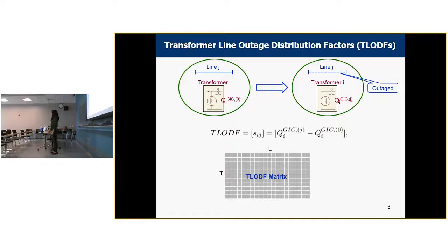So now the purpose of the algorithm that we developed is to minimize the total losses in the system. So for a network, we want to use line switching to minimize the losses. And the question is, what are the best lines to select for opening so the losses are minimized? We use a sensitivity analysis to find the best lines.